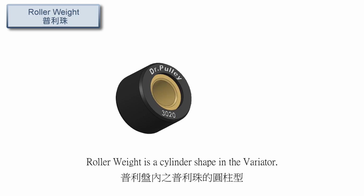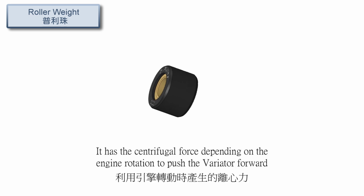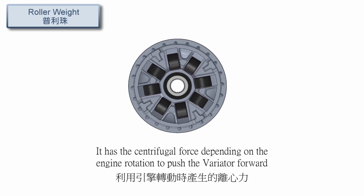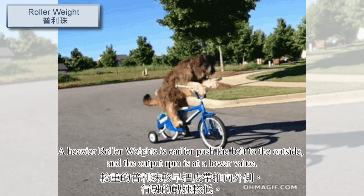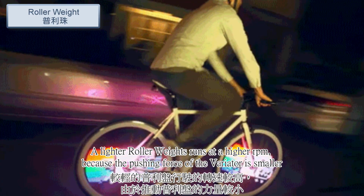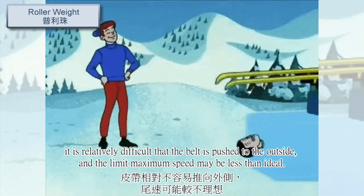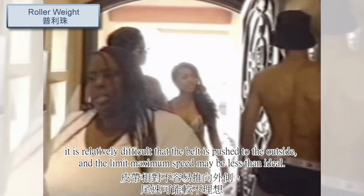A roller weight is a cylinder shape in the variator. It has centrifugal force depending on the engine rotation to push the variator forward. Its weight is chosen to control the timing of the speed change. Heavier roller weights push the belt to the outside earlier, and the output RPM is at a lower value. Lighter roller weights run at a higher RPM, because the pushing force on the variator is smaller. It is relatively difficult for the belt to be pushed to the outside, and the maximum speed may be less than ideal.